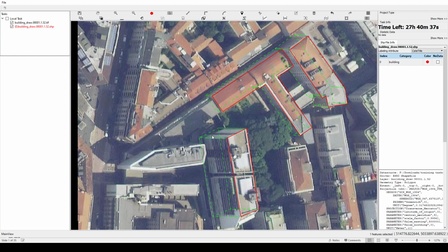Okay, so it has a different vector, this and this, but I could copy the vector of this to inline with this. Okay, I select that one, I press 3. See, building vector is set, so it will copy the vector for this one. And then I could select this, and then I press 6.